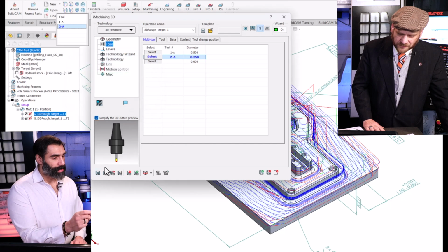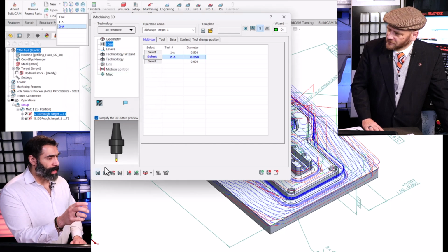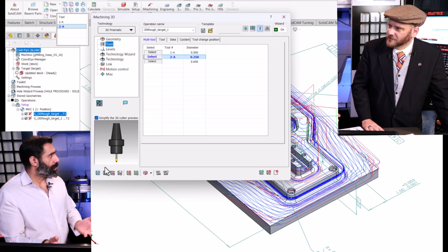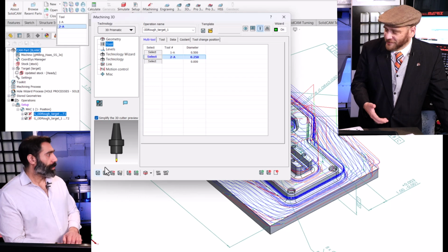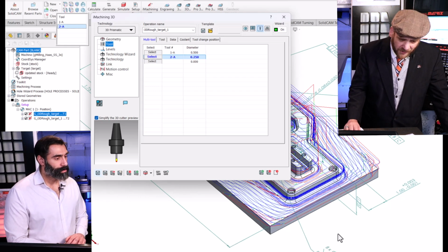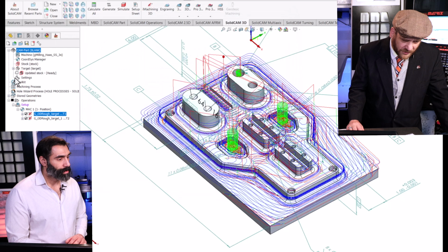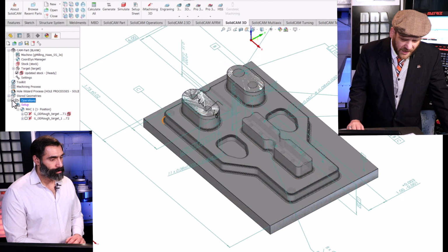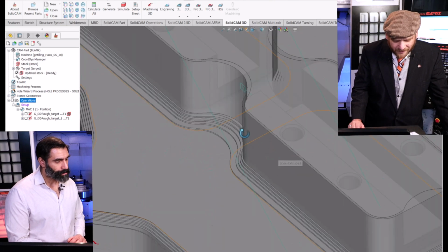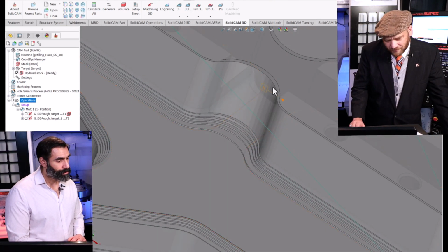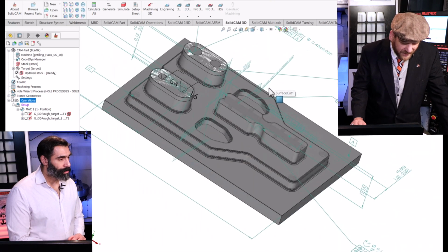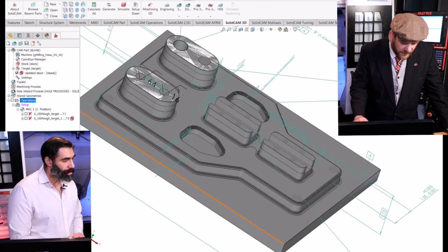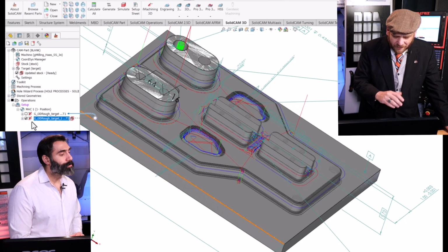Also, what I'm noticing here is that what would otherwise have been a kind of a 3D roughing operation followed by a rest machining, all you have to do was select the 2 tools and it does that for you. Yes, I set up the strategy in advance. So rather than sitting through the simulation, what I'm going to do is turn on my automatically updating stock model, which is a feature I really love. And you can see here that this first toolpath, that 1/2" tool, could rough out everything but really in between here. So it came in with just that 1/4" tool and removed the rest of the material.